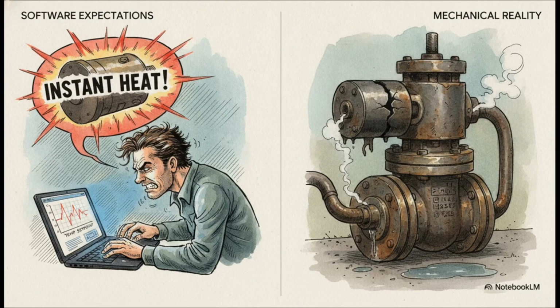Well, here are the most common mistakes we see technicians make. First up, overtuning for an unrealistically fast response. Look, you cannot force a massive boiler to heat up instantly, no matter how aggressive your software loop is. Second, ignoring those inherently slow thermal response times we just talked about. And third, and honestly, this is a massive one, failing to check for mechanical failures first.